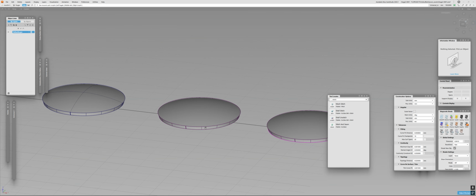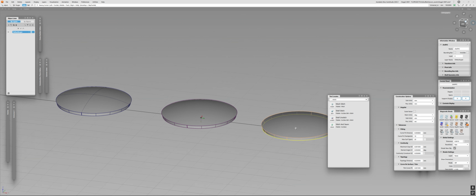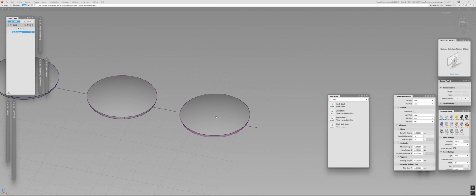Now, in terms of the surfaces themselves and how they operate, as you're going to see, I can't really modify. I can't even activate any CVs or anything like that with this model. They are still surfaces, still separate. You can easily convert it back, actually. So all of this information is saved, but Alias strips away the options to change that, the same as any other CAD system, because all of them, with this current construction, have a very specific flag which treats them as a BREP.